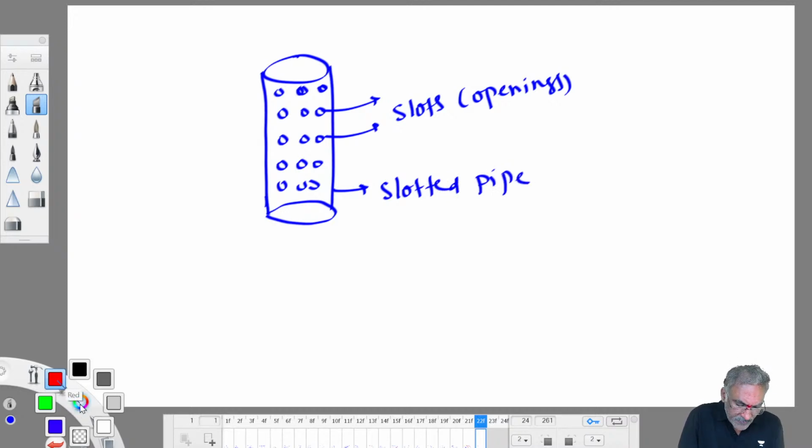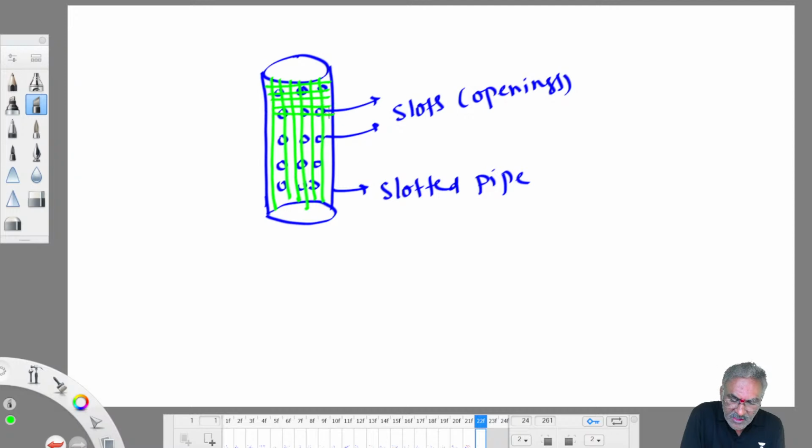So, to this what do we provide? We provide a wire mesh. It is bound with wire mesh. The purpose of providing wire mesh is to prevent entry of sand particles. Sand also moves along with water. To prevent sand particles getting into the well, because sand slowly starts accumulating in the well. What happens? The hole is filled with sand. It is completely subsided. Therefore, to prevent that, we provide one strainer.